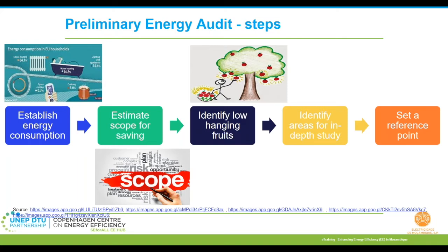With a quick look into production patterns, occupancy patterns, maybe even the EMS data already present, and more often through discussions with facilities personnel, the energy auditor would be able to come up with certain measures which may result in some immediate savings.